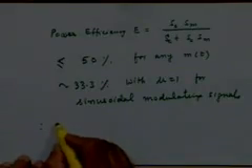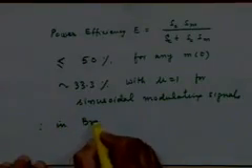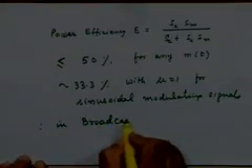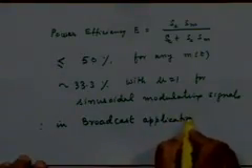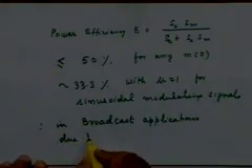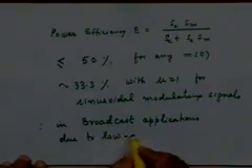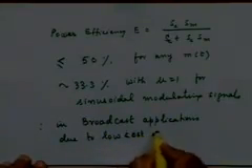So the real application of this kind of thing would be where? In broadcast applications, right? When you're transmitting at one transmitting station and a large number of people are tuning into their receivers and trying to recover the demodulated signal, right? So therefore, the power inefficiency can be tolerated in broadcast applications, due to the low cost of the resulting receiver.